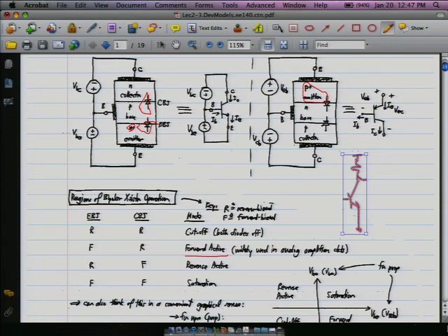Or it could go up to 3 volts, the supply, except for the fact that at the point you do that, there's no current flowing. So usually, as we're choosing this resistor value, we'll want to set this node right in the middle at around 1.6 volts. The purpose of this isn't necessarily to explain the circuit per se, but just to give you an idea of the range of voltages that we're usually working with on something like this.